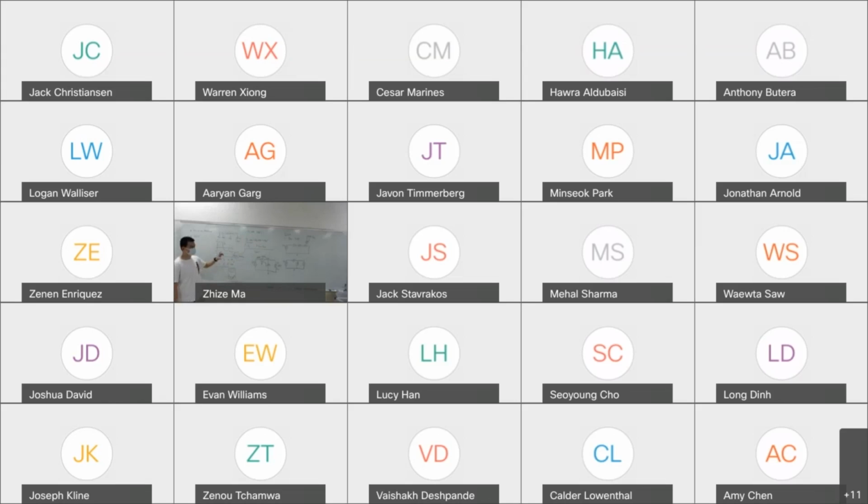That's for the DC signal. So for example, there's a resistor, you have some voltage across that resistor, you have some current across that resistor, then the resistor consumes power. That's the same thing for an AC signal. You will need to know the RMS value of the AC voltage across the resistor, and the RMS value of the AC current across the resistor. Then you know how much power is dissipated by this resistor. So that's why we need to use the RMS value.